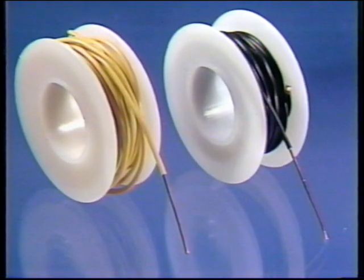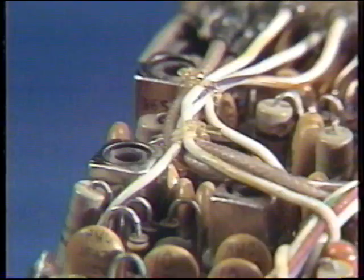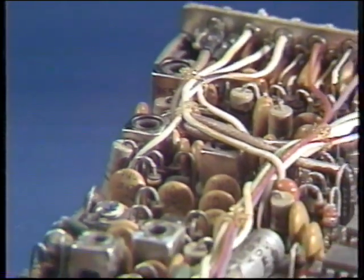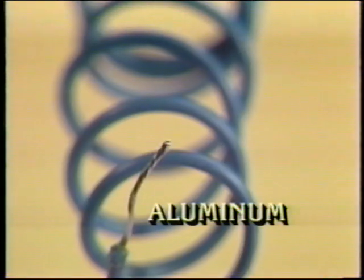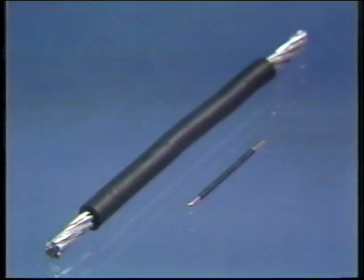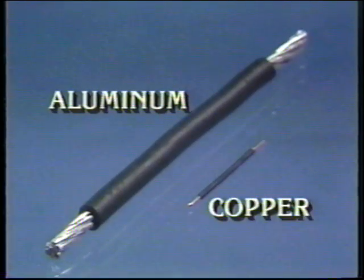Copper wire is the most widely used electrical conductor in aircraft. Copper has a lower resistivity than aluminum and therefore has a lower resistance. However, where current requirements are high, aluminum wire is sometimes used. Although a large conductor is required because of the high resistivity of aluminum, the weight of aluminum is much less than that of copper.